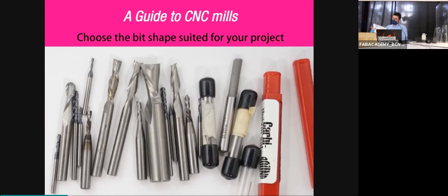And basically, you come and you say, okay, I want to cut aluminum, this type, I want to cut this depth, and you come with charts for which tool to use for each application. Of course, you don't need to know everything. I think that in my life, I have only used in total, more or less, 50 types of different end mills. A lot of them can be used for multiple applications. You don't need to get crazy, but there are millions of types of end mills for different geometries, different materials, different cuts, different outcomes. So choosing your end mill is quite important. Well, if you want to check it later.